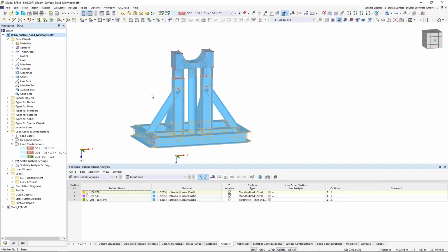What does it mean? Well, when you have a structure like that, you define the section. You define the material in the section. It's an assumption usually. You don't know if the, what do we have here? HEA 200 is enough. Is it too big? Is it too small? And when you run the stress strain analysis, you get a design ratio, maybe 20%. Then, if you want to be economical, you go back and exchange it for an HEA 160, and then you do the same again, maybe one or two times more until you find the best solution.